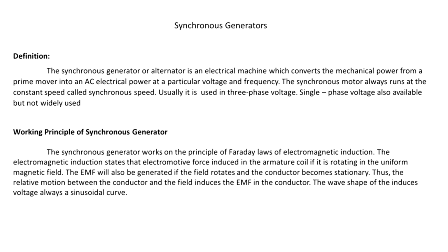Working principle of synchronous generator. The synchronous generator works on the principle of Faraday's laws of electromagnetic induction. Electromagnetic induction states that an electromotive force is induced in the armature coil if it is rotating in a uniform magnetic field. The EMF will also be generated if the field rotates and the conductor becomes stationary. Thus, the relative motion between the conductor and the field induces the EMF in the conductor. The wave shape of the induced voltage is always a sinusoidal curve.